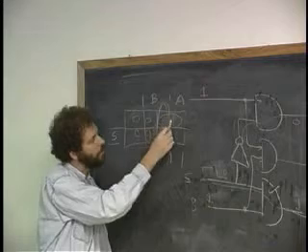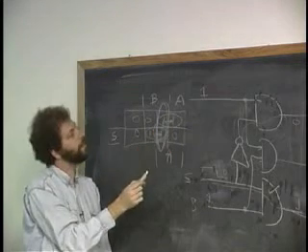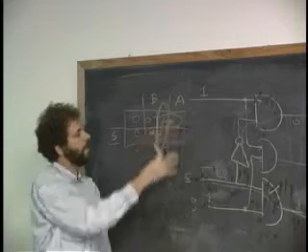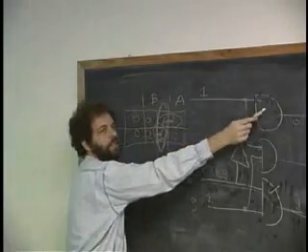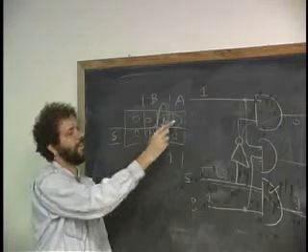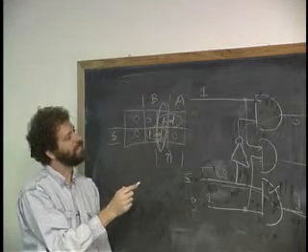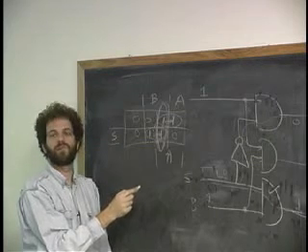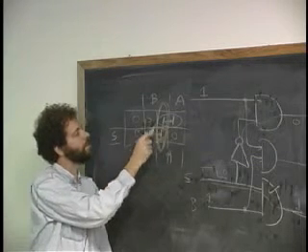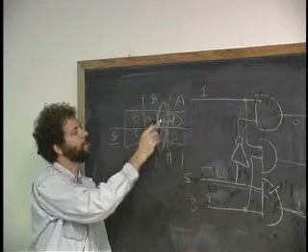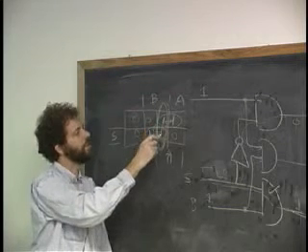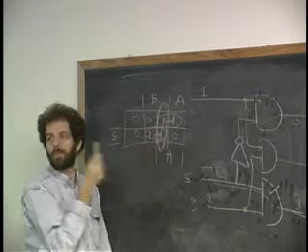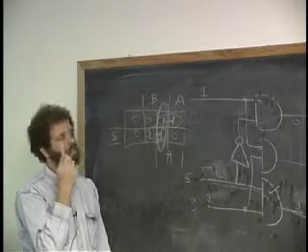Then when I go across this boundary, same deal, except that I have a circuit that doesn't care about B. It's A and S bar, this one up here. It is intuitively obvious that I cannot get a 1-1 hazard as long as there is a continuous path of stepping stones of these islands such that I never have to leave one before I enter the next one. But with that very same circuit, you could get a 0-0 hazard.